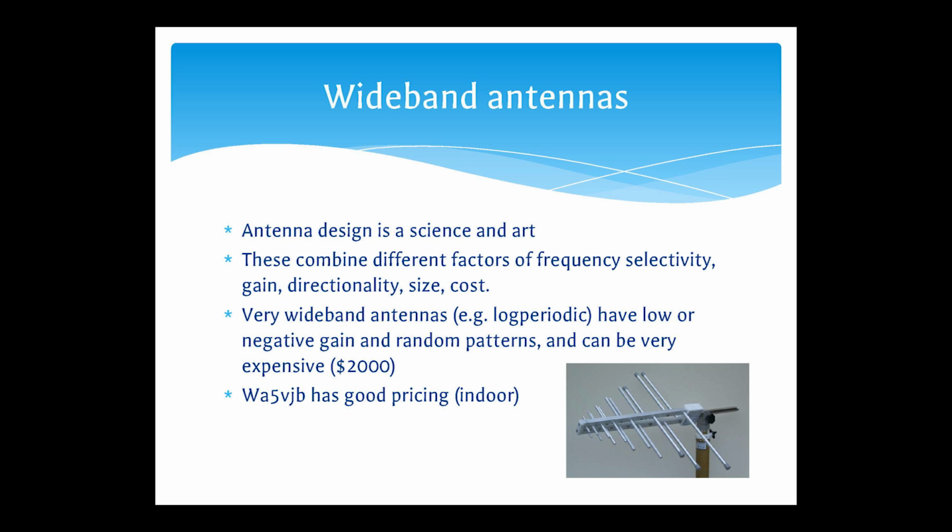Wideband antennas are more difficult to do in antenna design. If you're optimizing for bandwidth, you lose a lot of other antenna focuses, like low cost or low size or even high gain. So most wideband antennas are either very expensive, very low gain, or have other drawbacks.